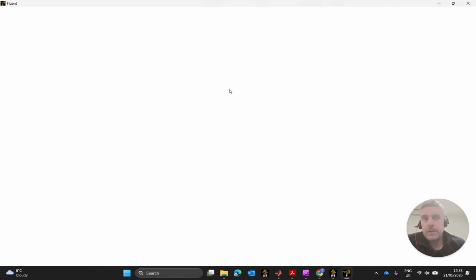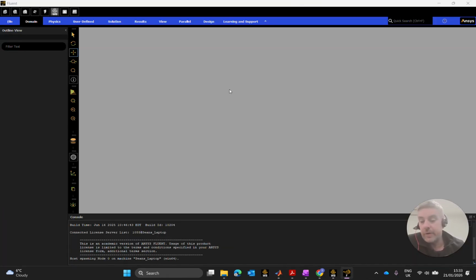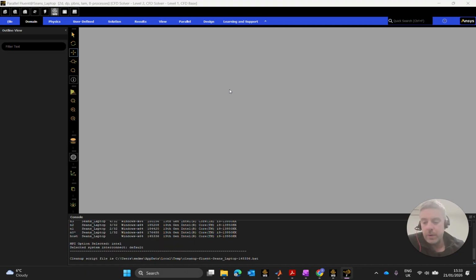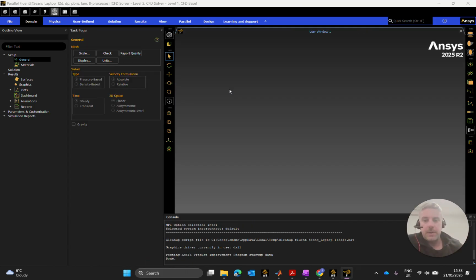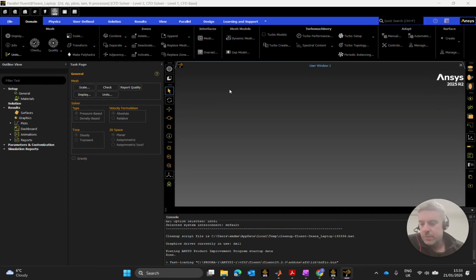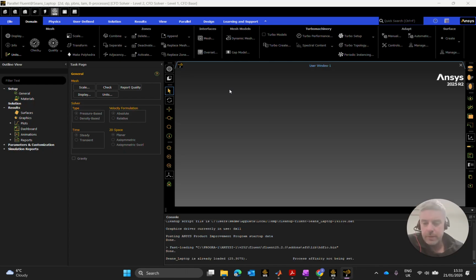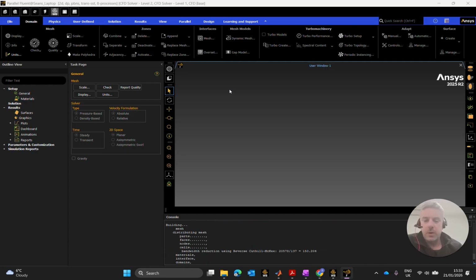So we'll look at this, which is slightly flatter, more parallel to the flow, at an angle of attack of 3 degrees. So hopefully we don't see that laminar separation bubble just as prominent in it. That will probably be there. It's obviously starting to separate.